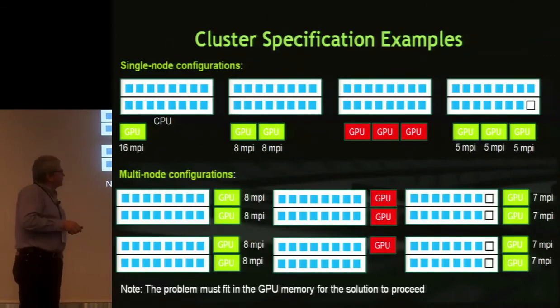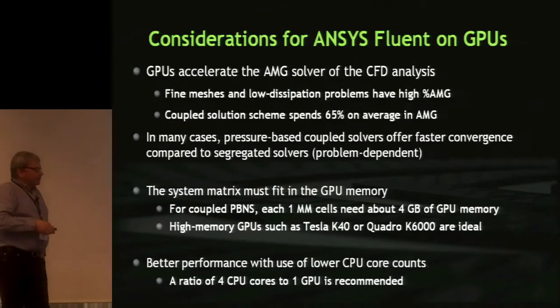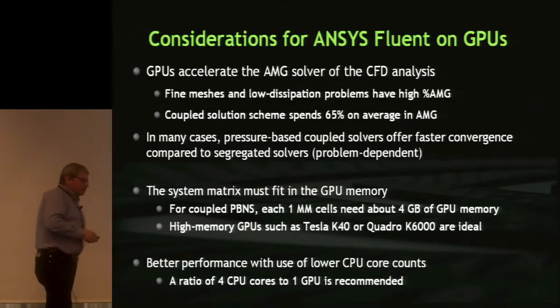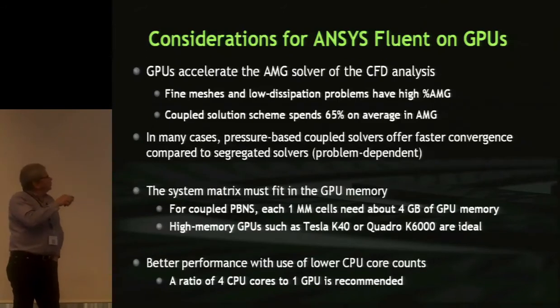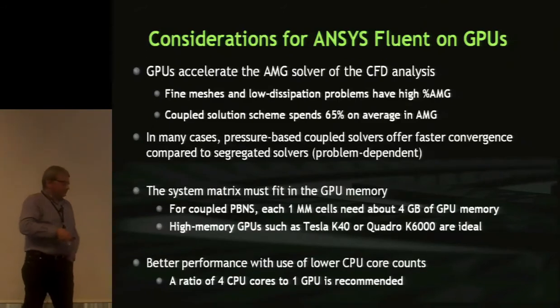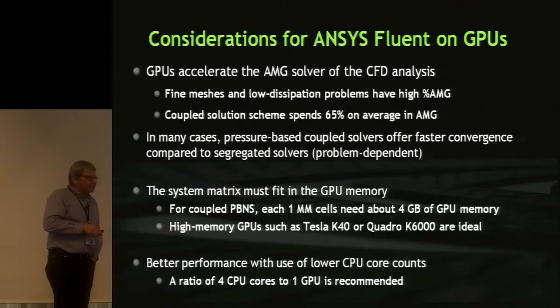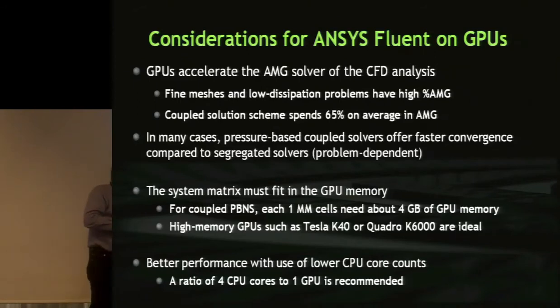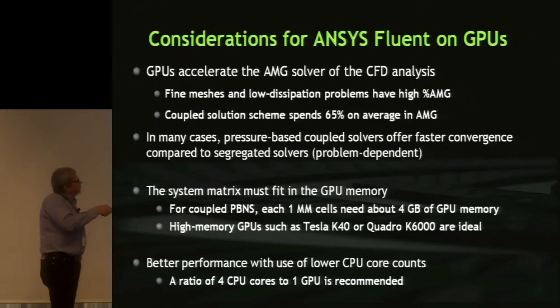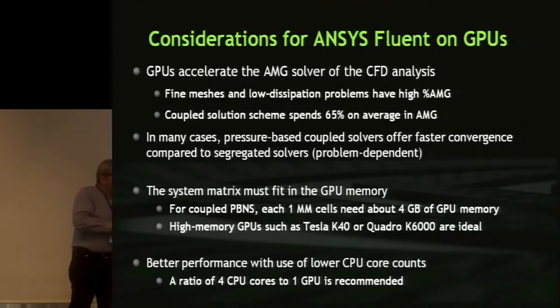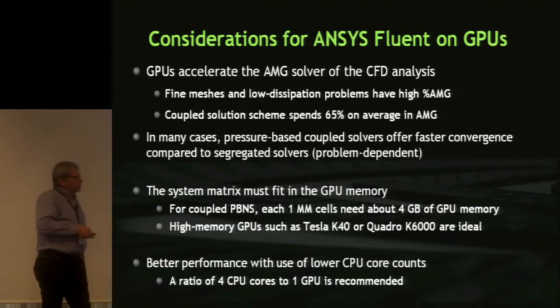Some considerations for ANSYS Fluent on GPUs. The AMG solver will be accelerated by GPUs. Fine meshes and low dissipation problems often have very high AMG solver times, computational load.